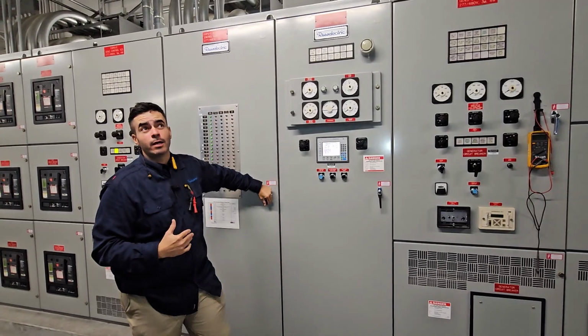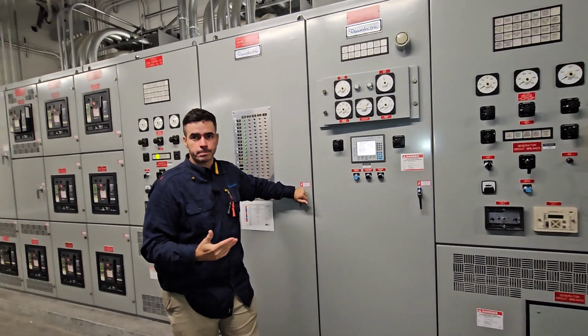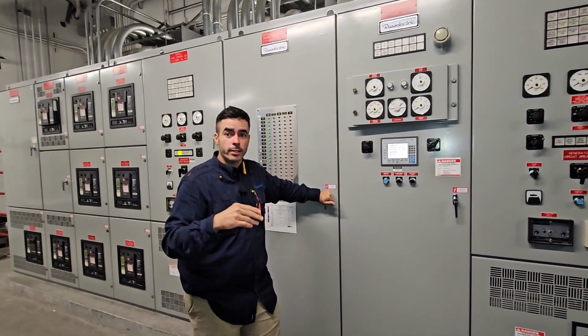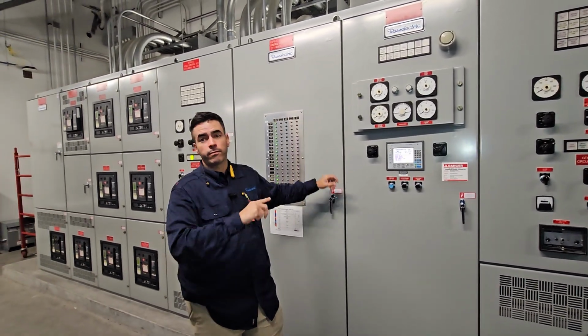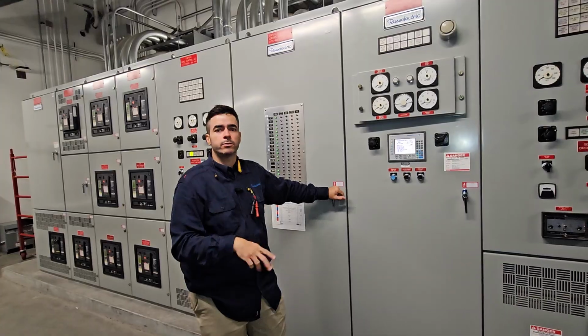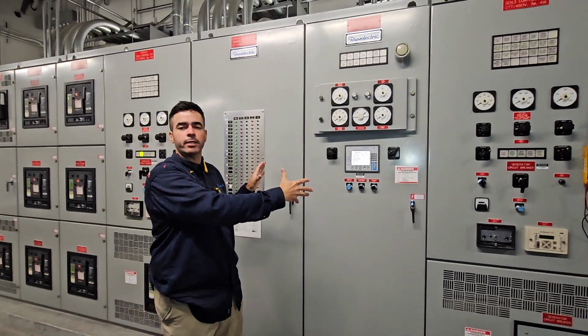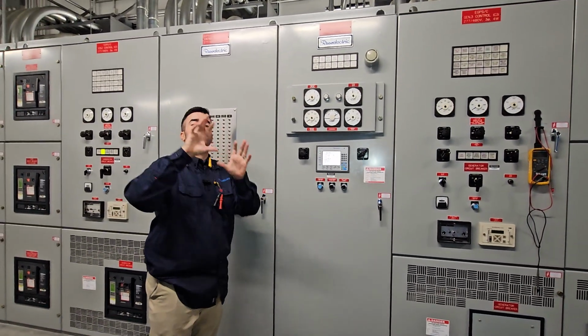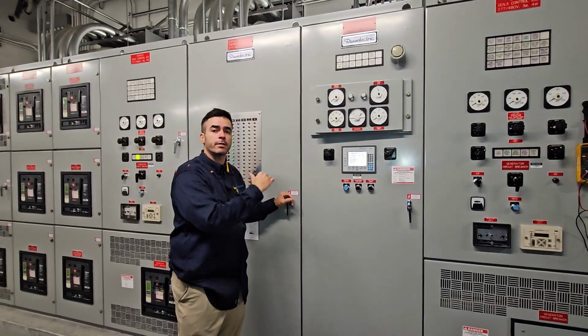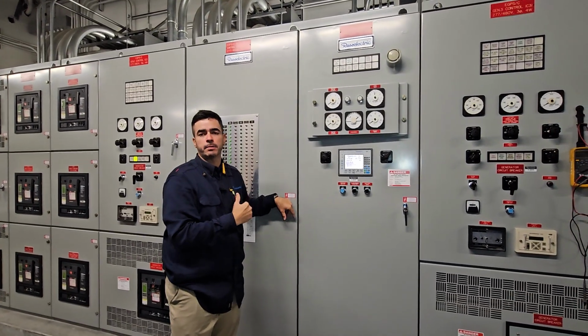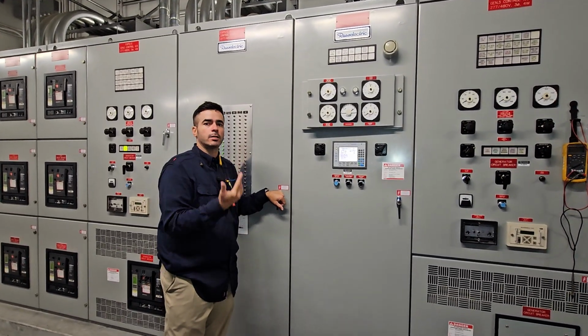It's a make-before-break condition. And it takes a long time because it's looking to be in sync. We talk about syncing here between the generators, well, those ATSs also look for sync between utility and generator power. That's why sometimes they take a long time.